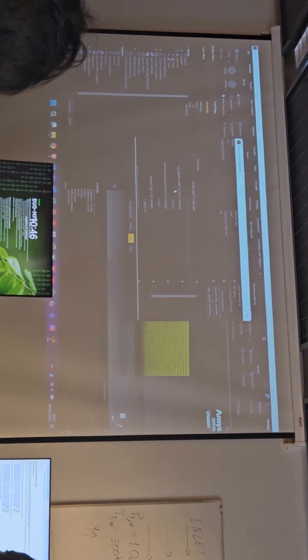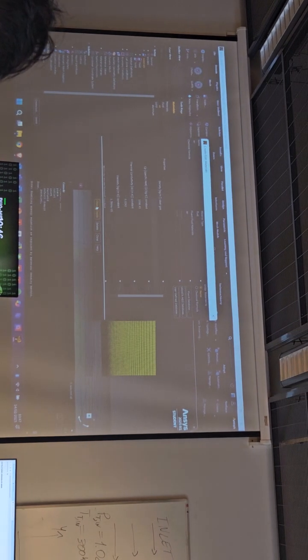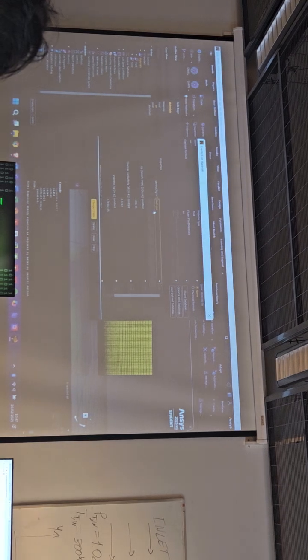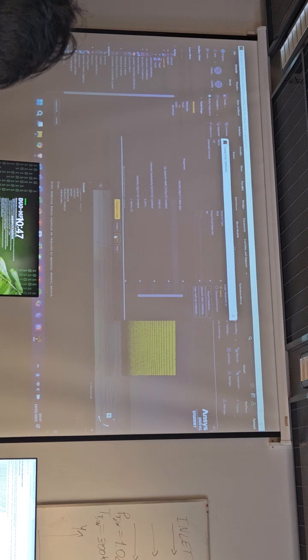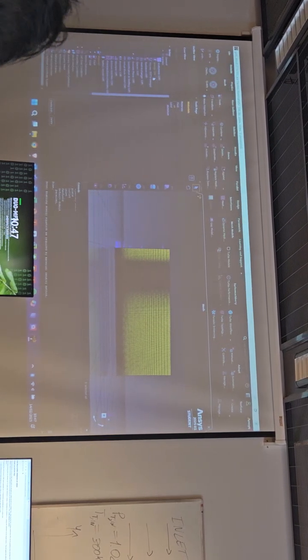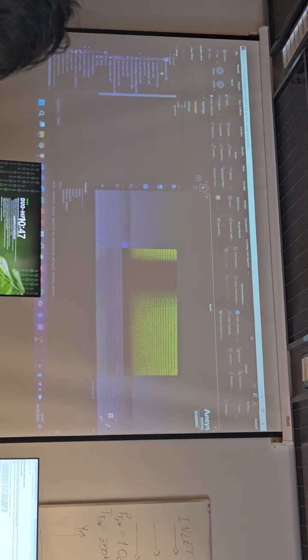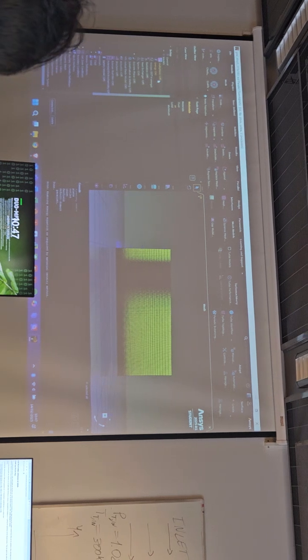And that's because when I hit change create here, so I change its density to ideal gas and change create to apply that, what happened automatically is that now the energy is on. That's because you need the temperature to solve the equation of state for air.